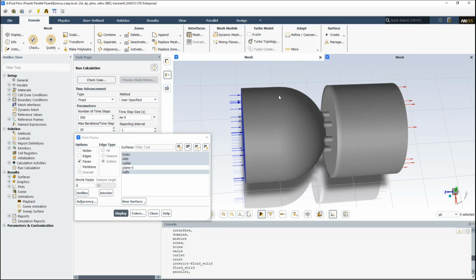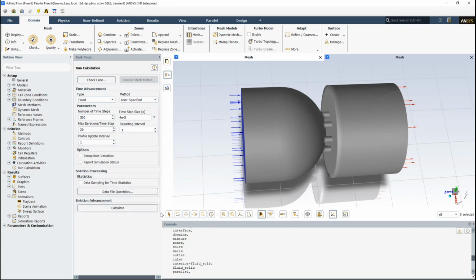And so what happens in that case is the flow comes in, it gets squeezed through these channels, it increases in velocity, and then as it leaves these, it becomes turbulent. That turbulence creates pressure fluctuations, and that's what sound is, right? So sound is pressure fluctuation. So in order to pick that up, we really needed to pick up some of the actual turbulent length scales to see what the pressure fluctuation was in those regions.